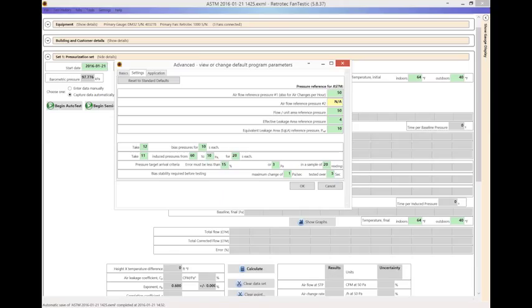And then in the bottom, it says, when can I gather my data? Like if maybe I'm trying to get to 60 pascals, but I'm only at say 55. This actually will determine that you need to be within 15% or 3 pascals. All right. So that determines when you can actually start gathering your data, and within a sample of 20 of them. So it says within 20 readings, if I'm this close to my test pressure, I can gather my data. And these are the defaults.